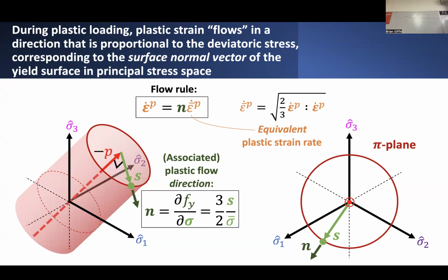If I have some deviatoric state of stress in the material, let's say I'm putting the piece of material into a state of tension, then the plastic strain has to increase in that same direction of loading, if you like. So if I'm putting it in tension, then I expect plastic strain is going to increase, corresponding to elongation of the material. If I'm putting the material in compression, reversing the direction of the loads, then we expect the plastic strain to decrease in the same direction.